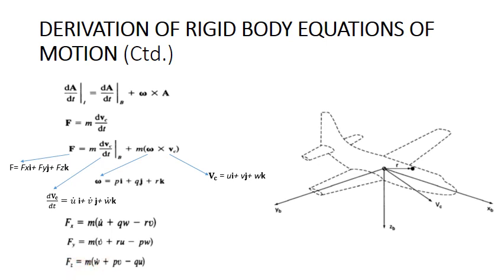Notice that each of these terms has the dimensions of acceleration. This is u dot, so its units are acceleration. q is angular velocity, radian per second, times meter per second; w is the vertical component, or the z body component, of the linear velocity, meter per second, times radian per second.